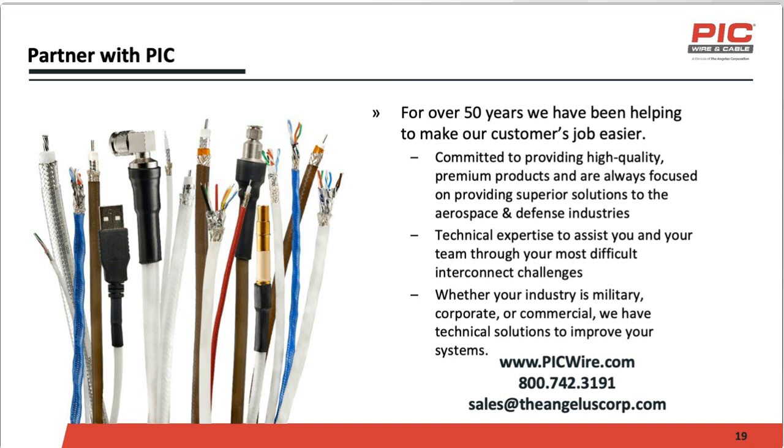Then there's a captive screw that you loosen up, which will release the cable, and then you can pretty much pull out the individual 22D contacts and repair them on an individual basis as needed. We're not able to demonstrate this on this live webinar, but if you go to our website, there's termination instructions in there, as well as a termination video, which shows you a real clear understanding on how to repair these in the field.